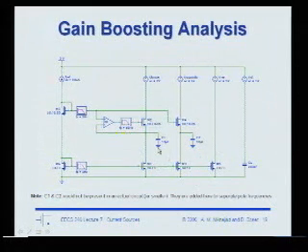And then you have this gain boosting. So you take this voltage and you gain it up by 10, and then you low-pass filter it and go into this device. Now this low-pass filter is very low frequency, it's 10 hertz. So we're actually purposely introducing a very slow amplifier here. Okay, that's a good thing actually. If I can show you that this idea works with an amplifier with only a 10 hertz bandwidth, you should celebrate, right? Why? That means you can basically run this at very low currents. Currents are not an issue, so you can do this with very little power penalty. Okay? All right, so schematic makes sense to everybody?